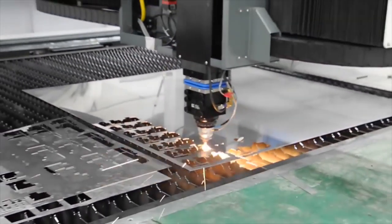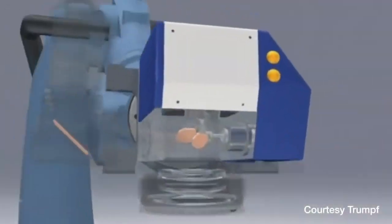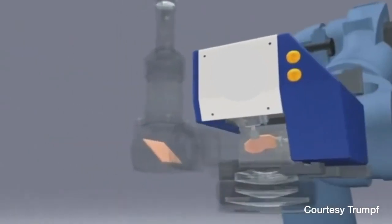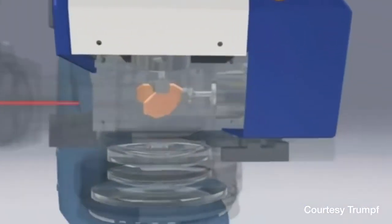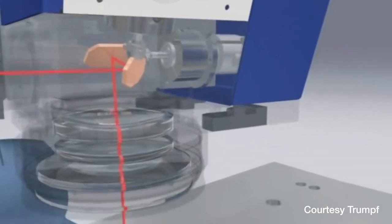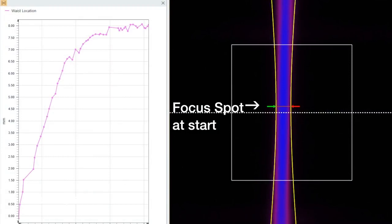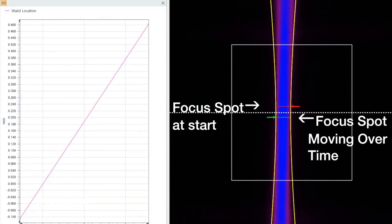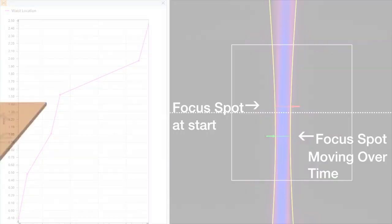The degradation of laser system components will ultimately result in a reduction in system efficiency. Laser power will likely decrease over time because laser optics and mirrors gradually absorb more laser light as they age or become contaminated. And because of the thermal effects that this absorption results in, the laser's optics will slightly change shape, and the focused spot will experience changes in size or location with respect to the process, known as focus shift.